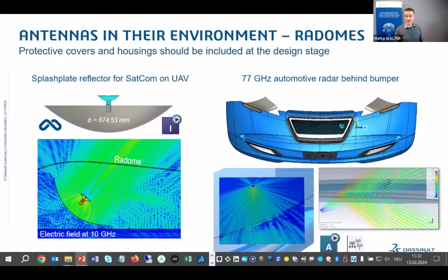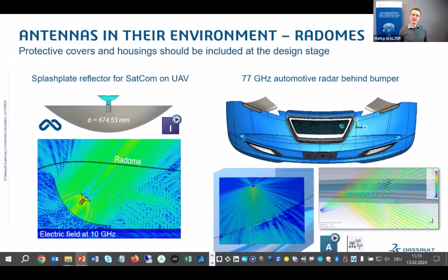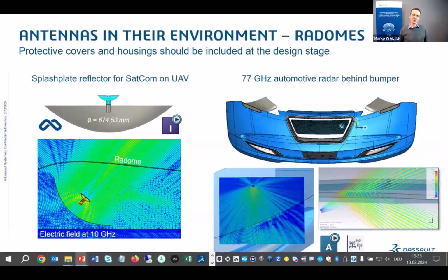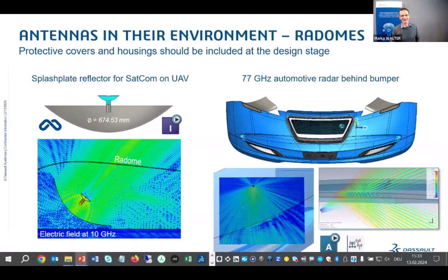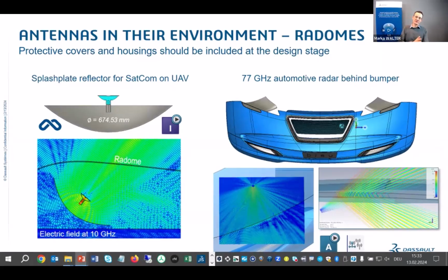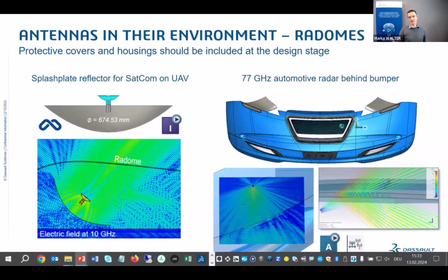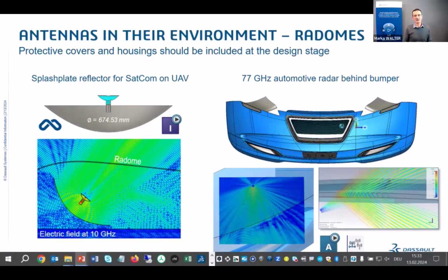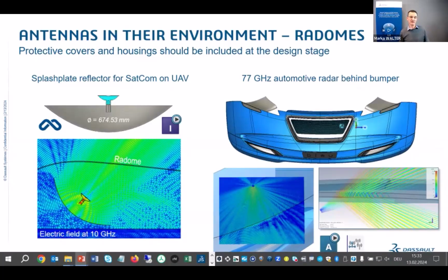We also typically, when we're placing antennas, need to protect them from the elements, so from rain or snow, hail, temperature, even lightning. And as such, the shaping of that antenna, or at least of the cover, its structural behavior or characteristics, its aerodynamic properties become important, and they act as a constraint for the antenna design. They influence the design of the antenna, and you might have to do a co-design of that radome shape and the antenna itself. So here, again, two examples.